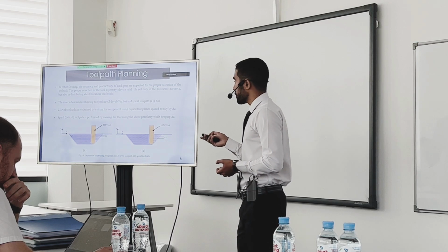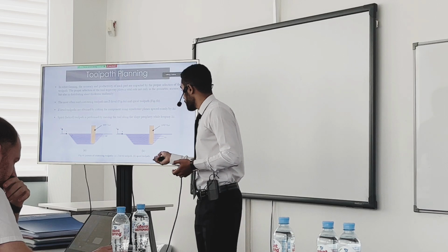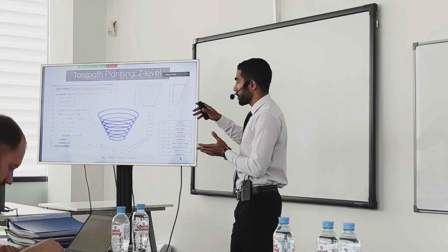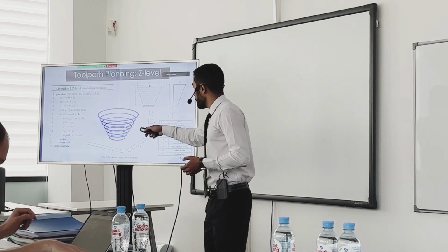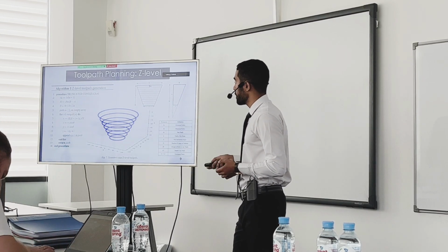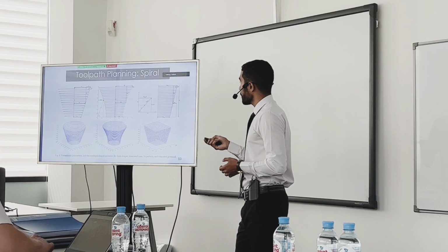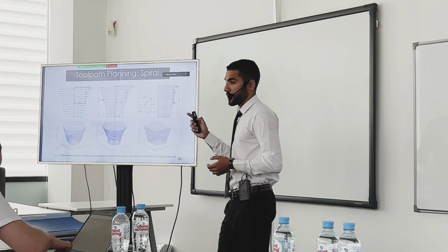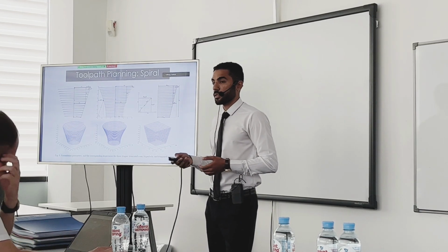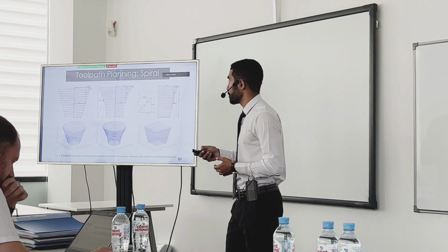And the most often used contouring tool paths are the Z level and the spiral tool path, which are presented here in figure 6. So for the Z level, it's like some consecutive layers spaced by delta Z, for example, which is the step depth, and it can be created using the presented function. However, the spiral tool path, which is a helical tool path, is better suited for the incremental sheet forming because it tries to distribute the sheet uniformly.